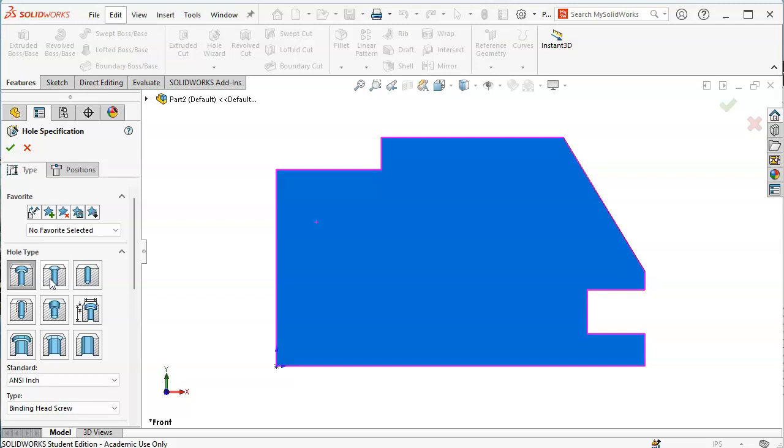Let's just say 2 or more components with usually a washer, so that the washer is the sacrificial piece that if it's going to gall, the bolt head, the nut has something to turn against rather than your probably more expensive part.